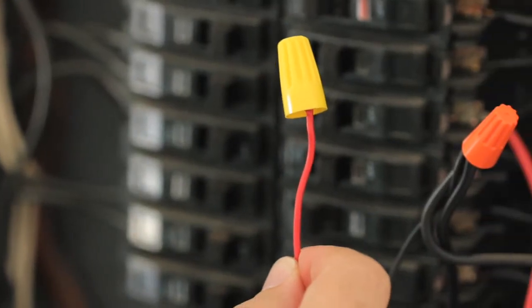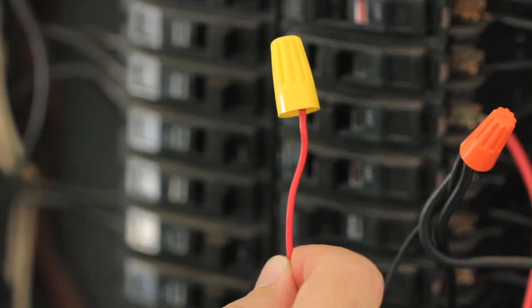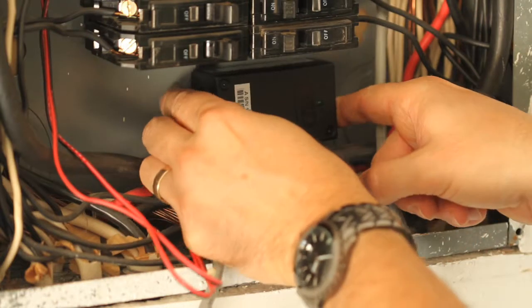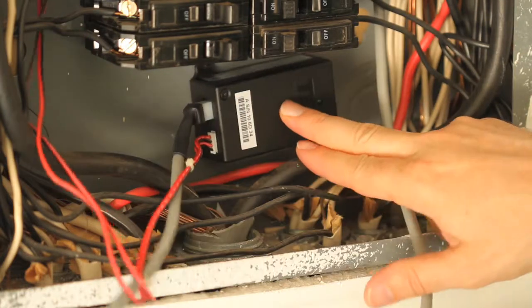Next, we're going to discuss power line communication. You should always have a few inline and plug-in noise filters just in case you encounter a noisy environment in a customer's home. We suggest that for most installations you plan to cap off the red wire and connect the MTU with just the black and white wires to maximize the signal. You may want to review the video on a 2-wire connection.